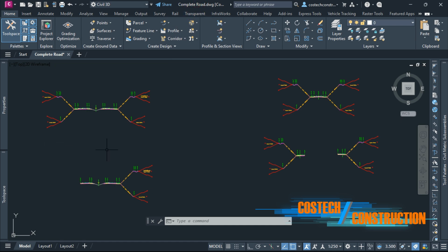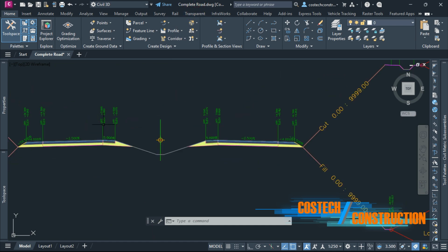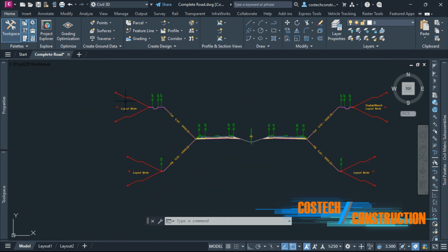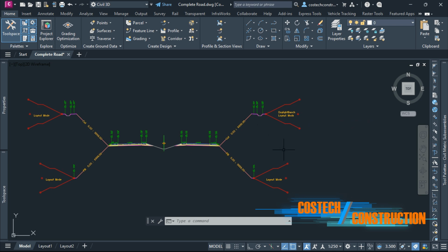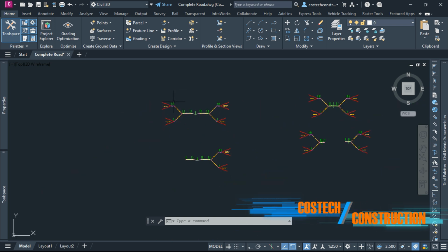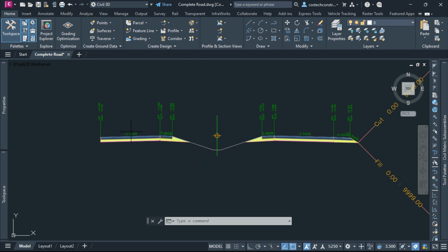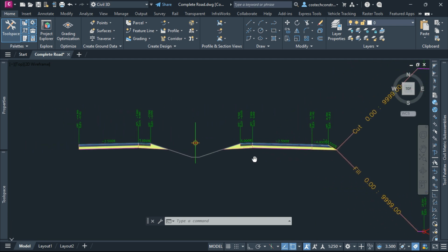In this video, we'll discuss how to create assemblies for an urban highway with a link road. This first assembly is for the main alignment and it has a depressed median as a separator. We'll copy the full Road 1 assembly to define the intersection assembly that will be used at the corridor region for the intersection in the next video.